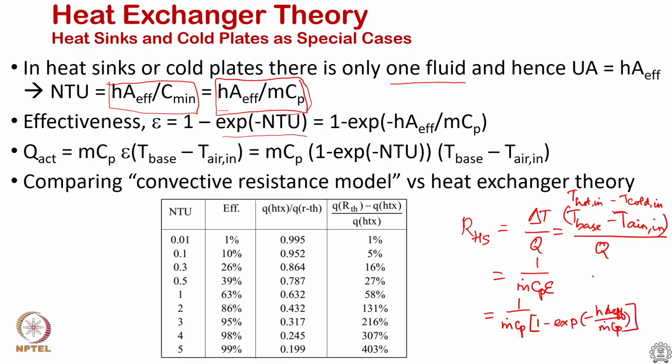So, this is the resistance of the heat sink. So now if I know my flow rate, I can calculate the heat transfer coefficient. I can also obtain my surface efficiency. You have mass flow rate known to you, specific heat is considered to be constant, and with this expression now I can calculate the resistance of the heat sink.